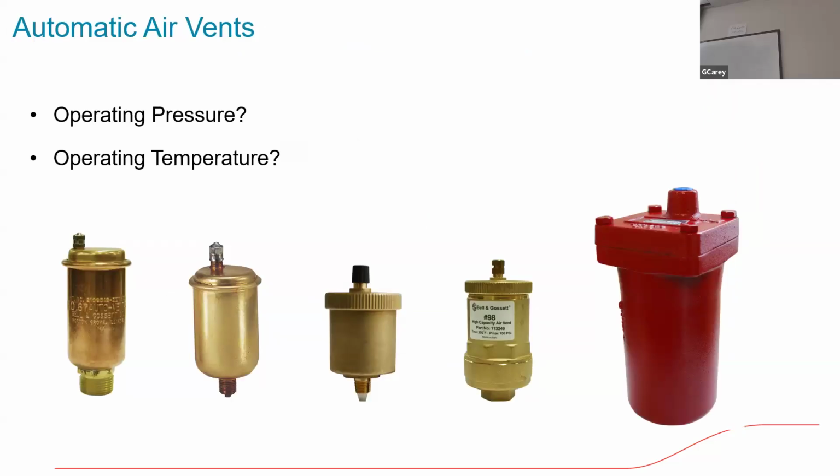I keep saying we're using these high capacity vents. There are all different vents that are available, in price and capacity, manufacturing, longevity, etc. This guy here would definitely be deemed a rugged, robust, commercial grade, high capacity float vent. But you'll see all different types, and internally they're all very similar, with the float and a lever that's attached to a plug or a port that's going to open or close the opening here that's going to allow air as it gathers at the top.